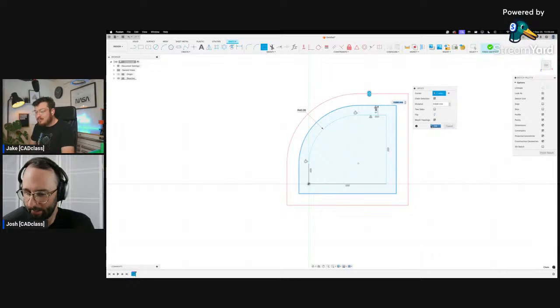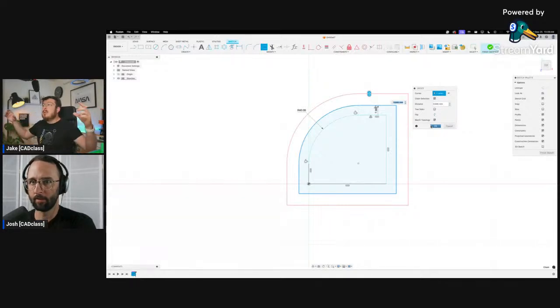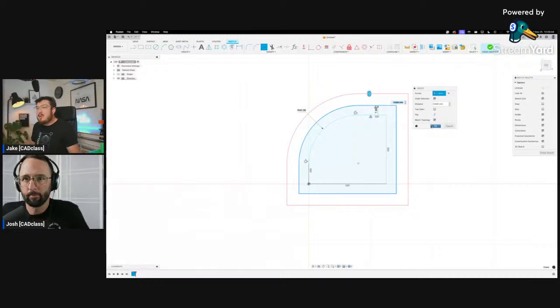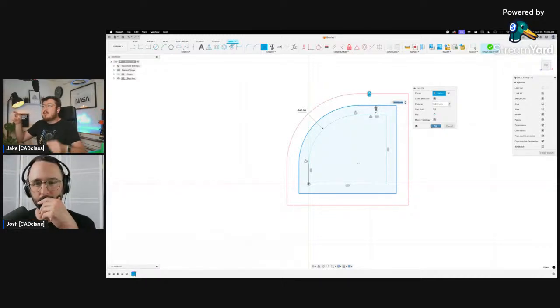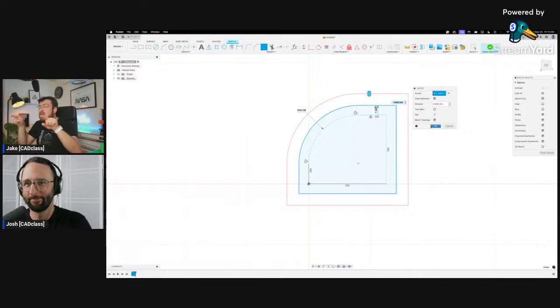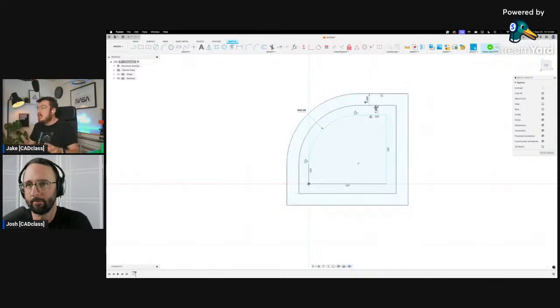What the hell does match topology mean? I'm reading it right now. It says limits the offset distance range. Weird. And maintains the topology of the offset so it matches the selected curve. Okay, why wouldn't it match the selected curve? Because if you imagine you have kind of like an infinity shape and you offset that from the outside, it just kind of gets this wavy racetrack shape. But if you offset it internally, then those dissociate into two kind of teardrop shapes. So they do become disconnected from the profile, which I get. Okay, that is really handy.